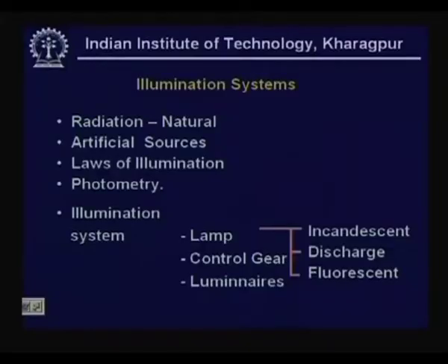And we saw that the need for moving from incandescent to fluorescence has come from another important requirement on illumination sources, in the sense that they ought to be economical, that is, increase the light flux for every watt of energy consumed. That is where the efficacy of light sources is talked about in terms of lumens per watt. Though in the case of discharge lamps we get a line spectrum or a band spectrum, in view of their higher efficacy they are preferred.